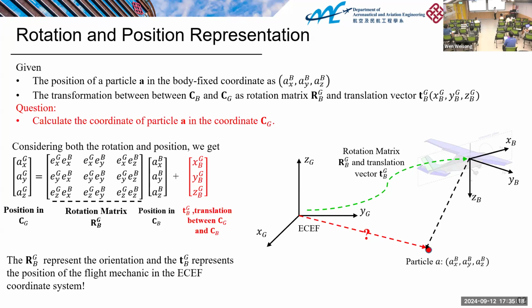As we mentioned, the rotation part is equivalent to the roll, pitch, and yaw. This is the 3x3 matrix. So first you do the rotation and then the translation, and this should be equivalent to the left side. In this case, we can easily transform one point from one coordinate system to another by doing the rotation first and putting it together with the translation.